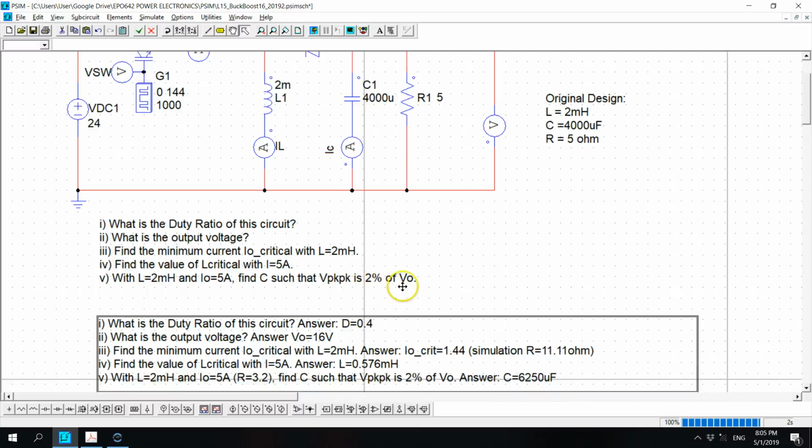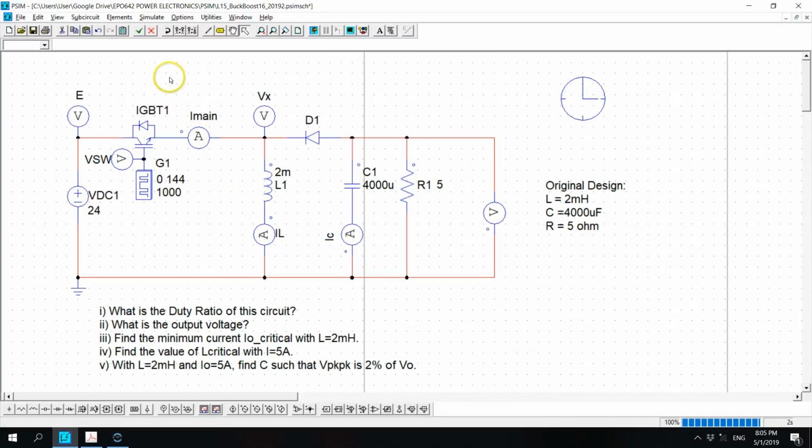And if you want to simulate that, of course you have to derive the R in the circuit. Therefore you can use V out, R equals V divided by I to get the value of R, and then you plug into the simulation circuit, and then you run, and then you can find the current. Okay, can I do that? So now let's run it together first.